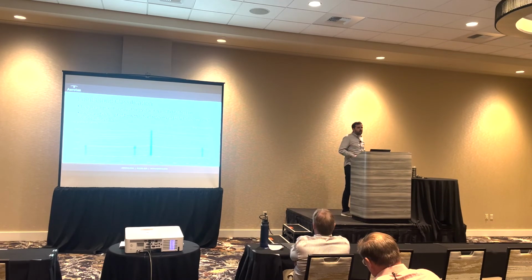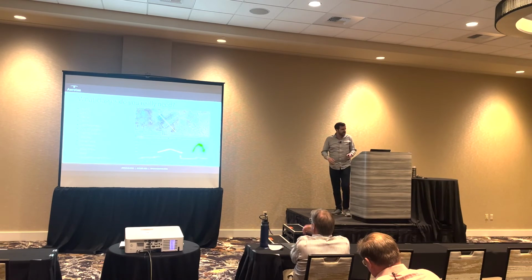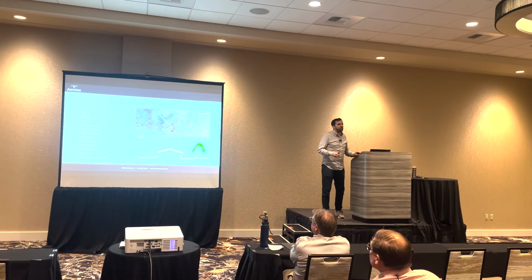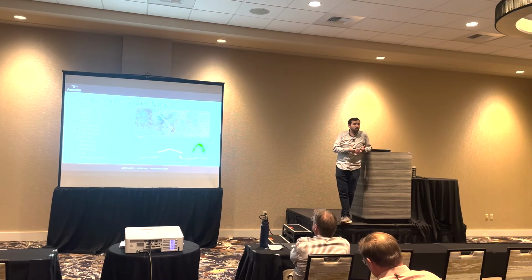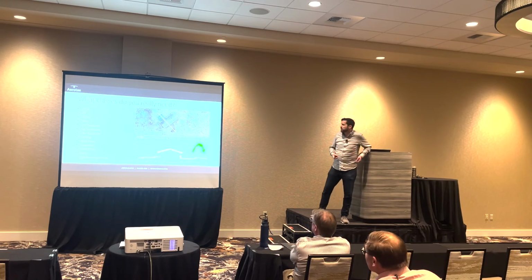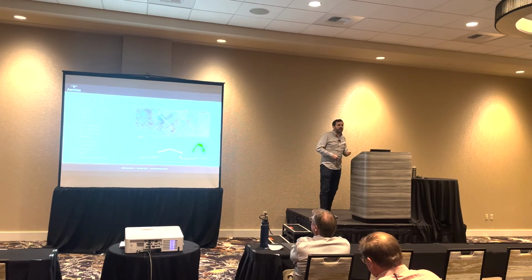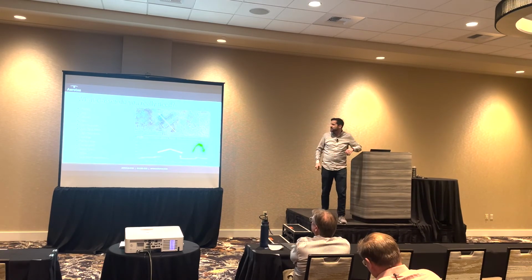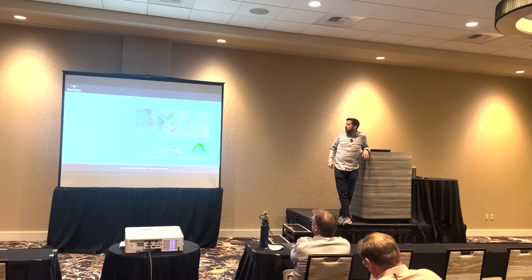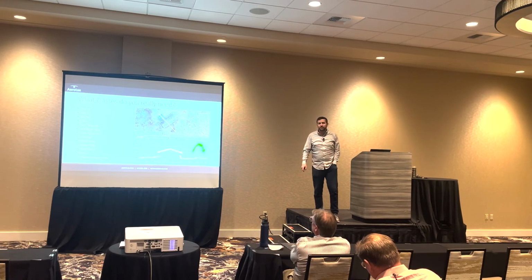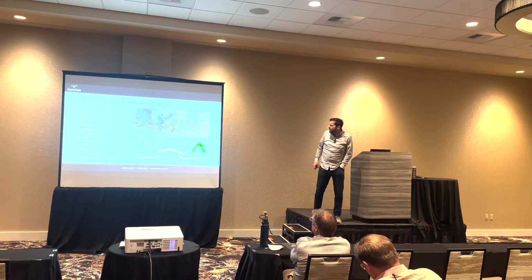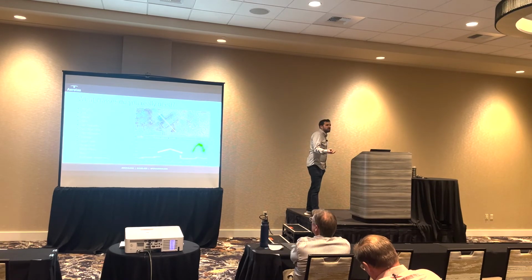The first question, though, is not how to classify the data, but to ask yourself, what classes do you really need? Do you need ground? Typically, that's the most valuable thing. That's the number one thing that people look for. Do you need it to be separated from roads? What about bridges and overpasses when there are multiple ground surfaces, and how do you deal with that? Do you classify low, high, and medium vegetation? Do you need those to be different, or does a single vegetation category work? Do you need buildings separate from everything? Power lines, et cetera, et cetera. Do you need the shield wires to be measured differently from the power lines? Different surveys have different requirements.